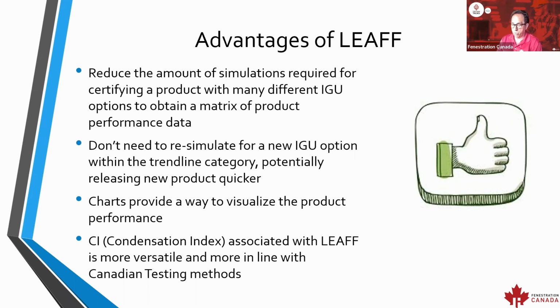Okay, a couple questions here from Jag. How do you determine the coldest part of the product? That's the nicest part of the new CI tool, that we're not determining it at all. The actual tool is running the therm model, and it's pinpointing where that is. Now, it is generally in the same location. There's a part of the frame that has to be half an inch away from the glazing gaskets, and on the edge of the window, it needs to be an inch away from the gaskets. So that's typically the coldest part, but it can be anywhere on the frame.